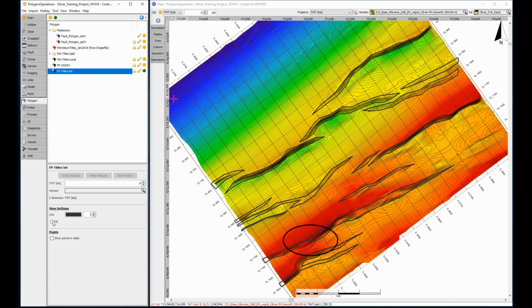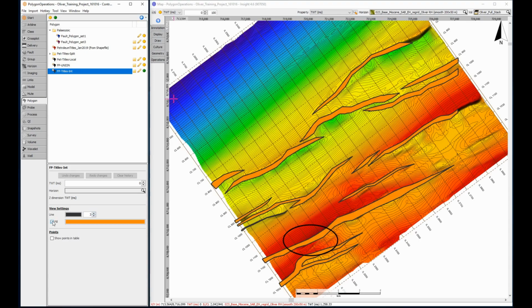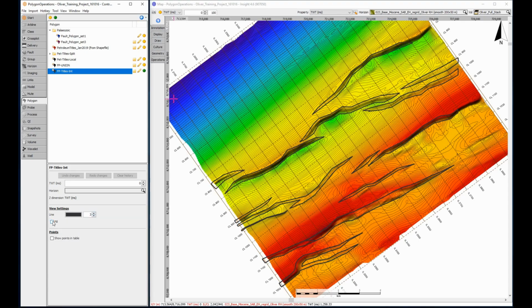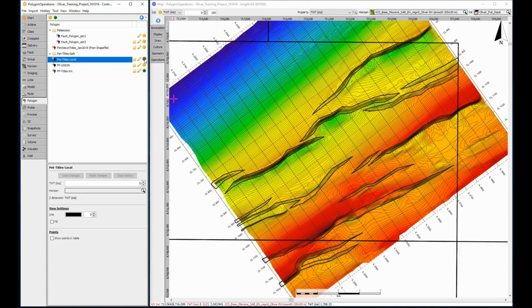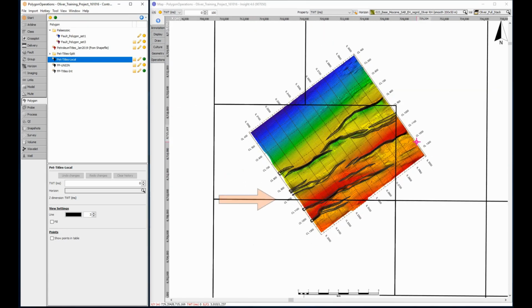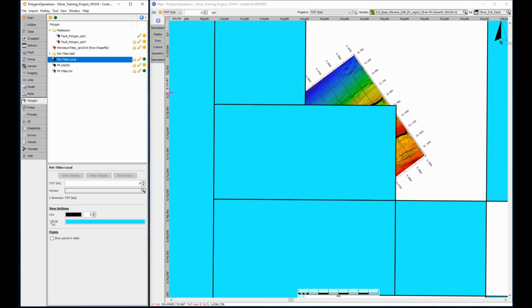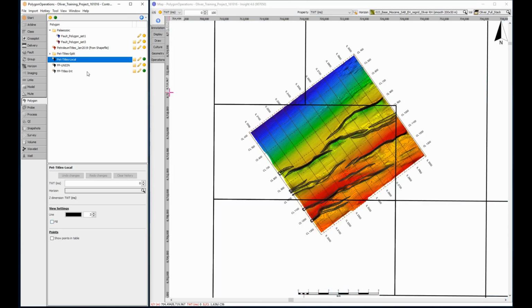With the polygon fill off, I see the southerly fault is actually 2 separate polygons, and with the fill on, it's a single polygon. In fact, Insight is being really clever here by creating 3 intersecting polygon shapes from one input shape. The lease boundary bisects the larger fault shape into 2 smaller fault shapes, one for each lease block. It also retains the original larger fault shape because it exists entirely within the multi-shape lease polygon.